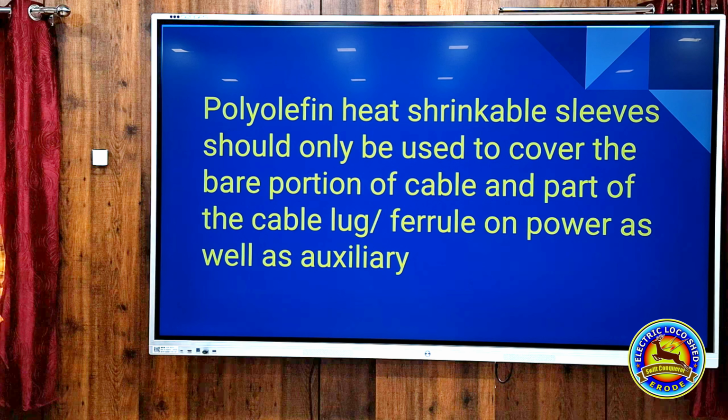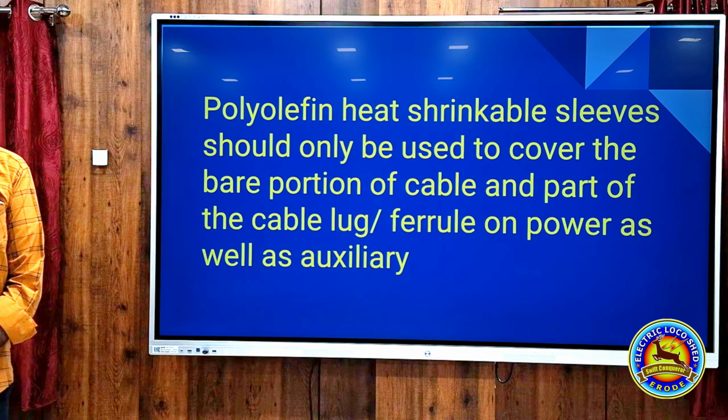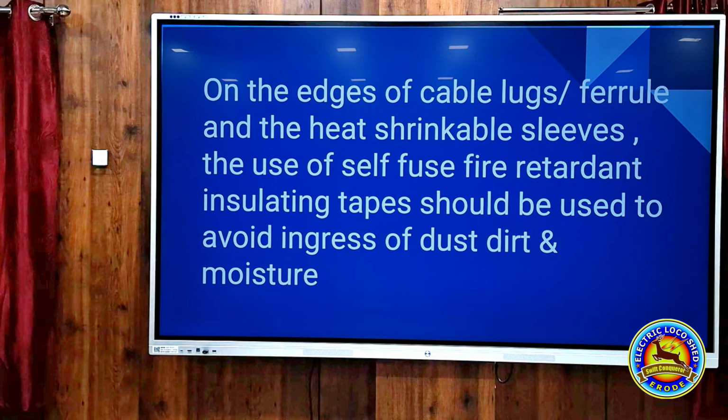We should not put insulation tape and keep the lug in open condition, because later on that will cause moisture entry and sulfation. On the edges of the cable lug or ferrule and the heat shrinkable sleeves, self-adhesive fire retardant insulation tape should be used to avoid any ingress of dust, dirt or moisture.